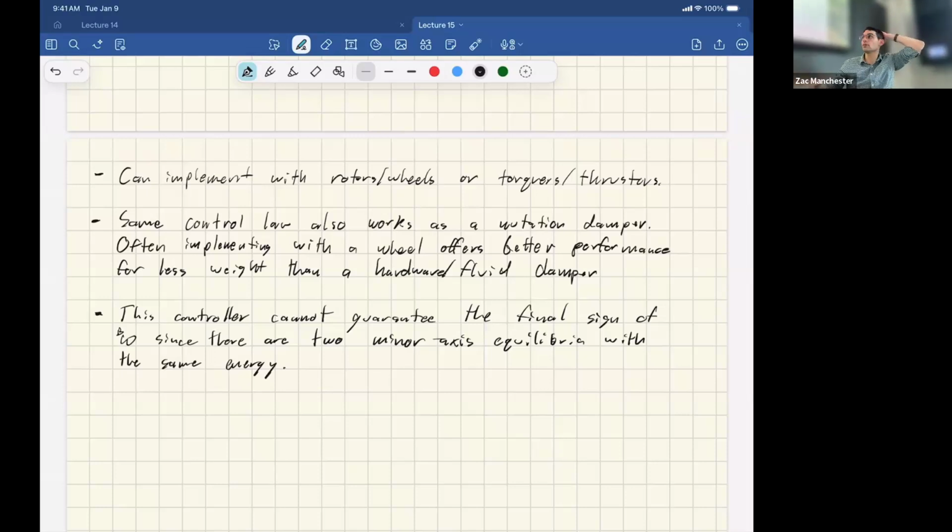And if you have different units on that, you can wrap whatever constant you want into this Jacobian to rescale the units. Okay, so if I add up all the thrusters, I have an input thrust force for each one. And then from a bunch of geometry calculations, I get the torque for each individual thruster.